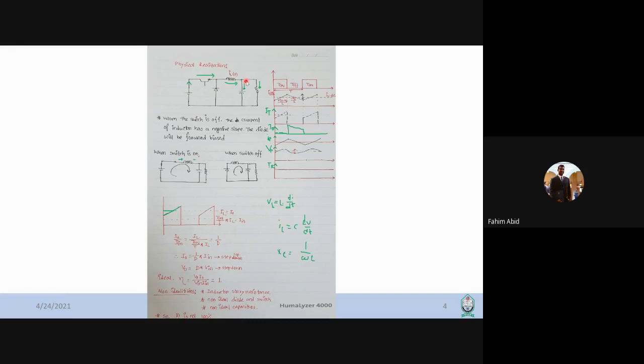All these components in real life will have certain resistances, and these switches will have some switching loss as well. So all these things correspond to the overall losses in the converter. Typically, for this kind of circuit, efficiency lies in the range of 90 to 95%.